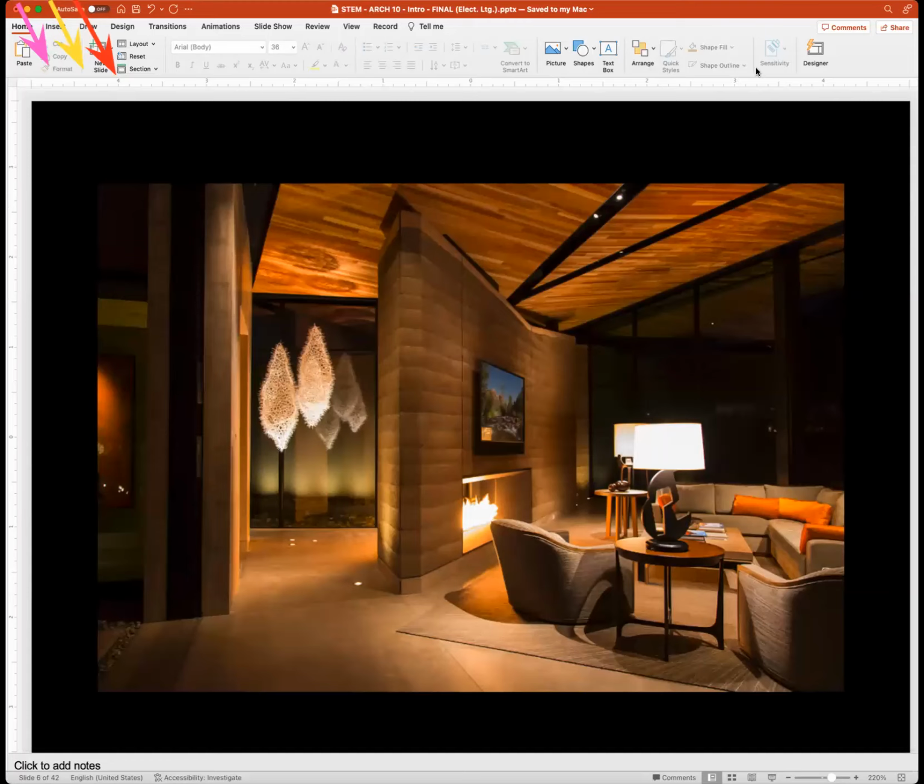We're not lighting the space in order to cause it to glow. We're lighting the materials. We're lighting a piece of artwork that's hanging. One of the things I want you to notice here also is that look at how we're lighting this actually from below. We're lighting the wall from below. We want to accent this beautiful wood. And here you can see we're putting the light into a cove so that the light itself doesn't become a distraction on the ceiling. I don't want to see the lighting. I want to see the impact of the lighting.